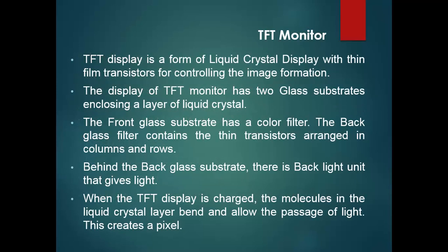Coming to TFT monitors, TFT display is exactly a form of liquid crystal display with thin film transistors for controlling image formation. These monitors also have two glass substrates or two polarized glass and a layer of liquid crystal sandwiched between those two glass.